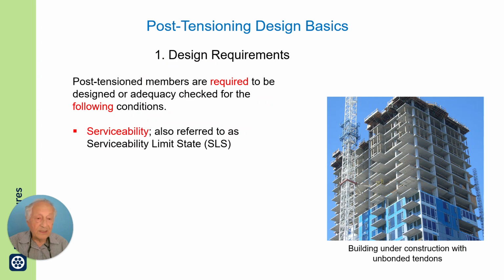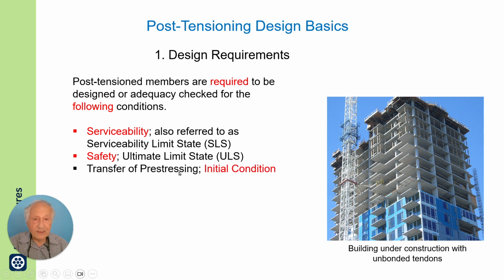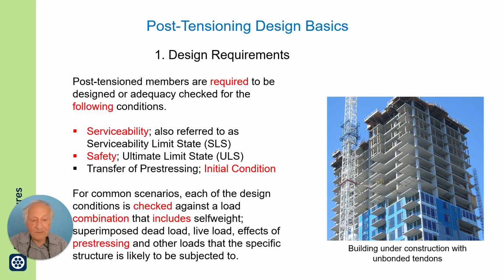could be detrimental. Now, starting with design requirements of a post-tension structure, universally, the design requirements address serviceability as one design step, then address safety as a second design step, and finally, initial condition, that is transfer of pre-stressing to the member.